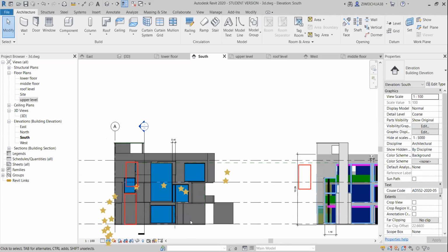I told you, in order to model this glazing, for example, the last one, this one, you have to host this big window in only one wall, which means you should not have a wall here and a wall here, because if you host a window like this, it will be a problem because there are two walls. The window should be hosted only in one wall. Same thing as you did here, actually. This one is correct because you removed the wall and you did it in one wall, big wall. So since you did this, I think you can fix this area also here.